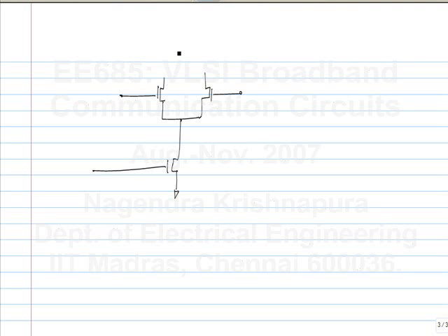When you want to do summation in the analog domain, the easiest thing to do is to sum currents, because of Kirchhoff's current law: you put all the currents through the same node and it does the summation. It's harder to sum voltages because you have to put voltage sources in series. So you do this, and the weighting is provided by the tail current I tail. Depending on the coefficient value you want, you choose the value of I tail.